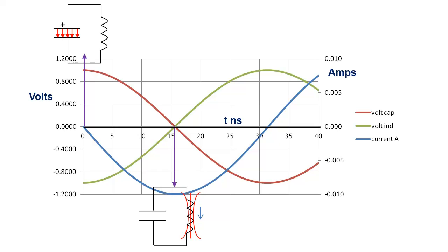Since the voltage across the ideal inductor is 0, the rate of change of current is 0 too. This is manifested by zero slope in the current, that is, the blue curve. The rate of change of current is 0 and therefore current through the inductor must keep flowing in the same direction, and has no option but to charge the capacitor. However, it deposits positive charge on the bottom plate and therefore the voltage across the capacitor becomes negative.